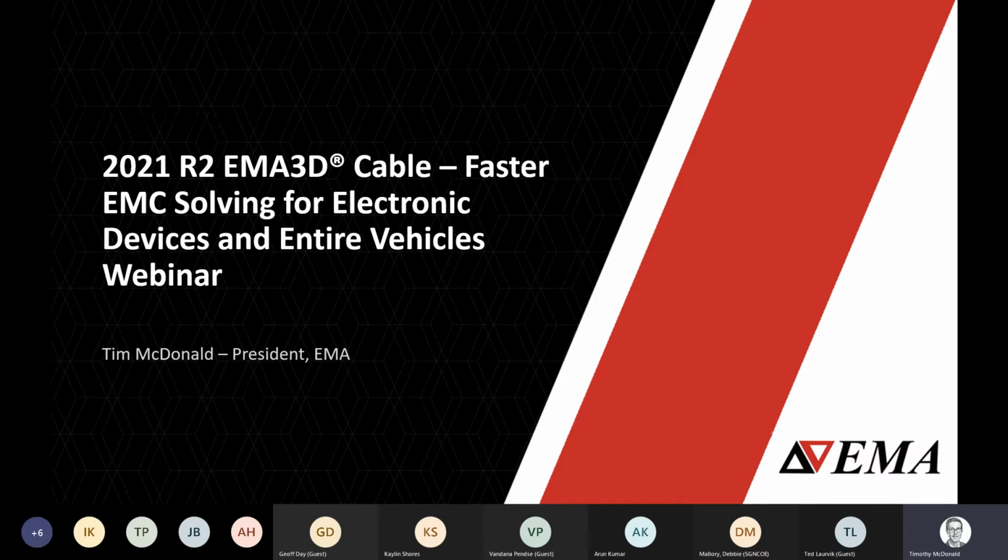A popular cable database software is Zuken E3. There are some other competitors. And EMA3D Cable is able to import the Creo path of the cable and assign each cable segment with the wire board information from the KBL export from, say, Zuken E3. That's a very popular workflow.